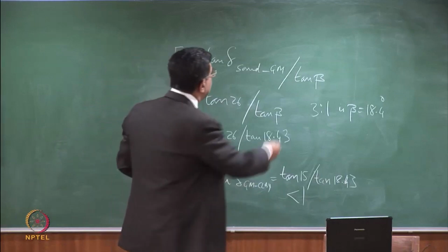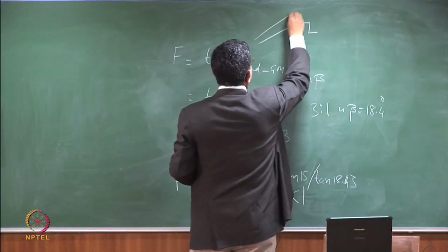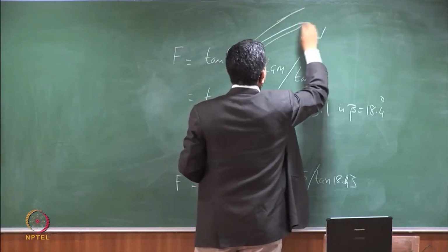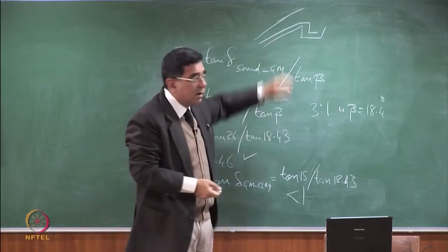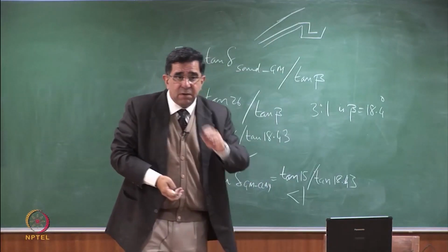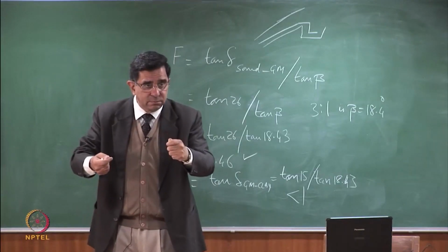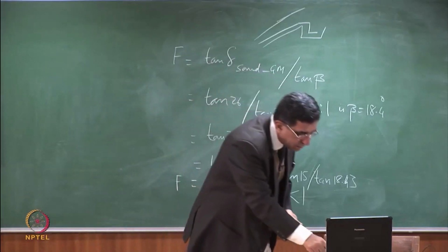Well, if the geomembrane is anchored at the top in an anchor trench, okay? It is buried in an anchor trench which is holding the geomembrane. We'll come to the design of the anchor trench later. But if the geomembrane is anchored at the top, it can take a T. Agreed? And what is the T that you need?